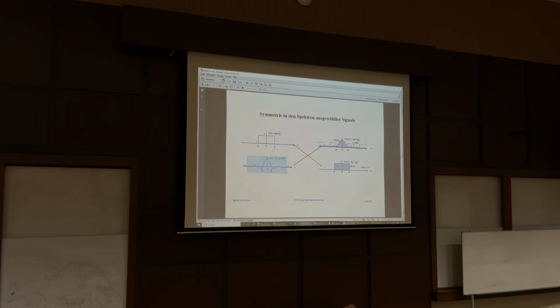If we put this sinus x over x as a time signal, we get the spectrum of the corresponding signal. Yeah? So there's a cross relationship. Rectangular pulse gives a sinus x over x spectrum. The sinus x over x signal gives a rectangular spectrum. That's quite amazing, and sometimes we use this relationship to find new spectral presentations.